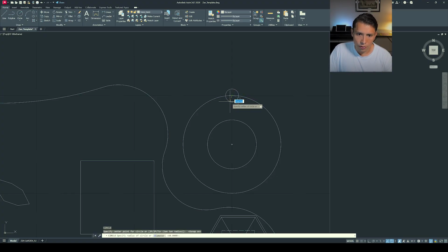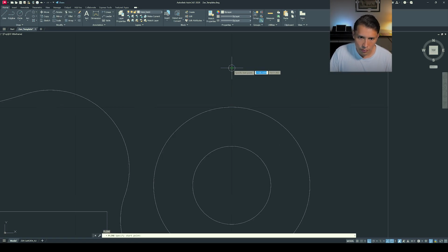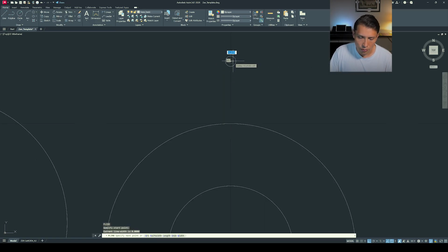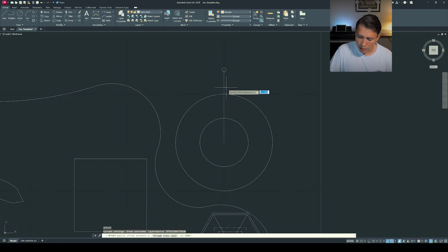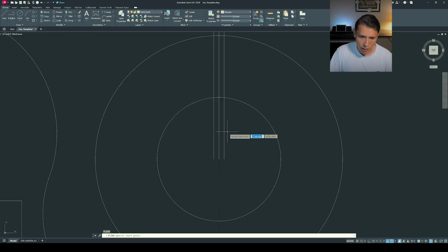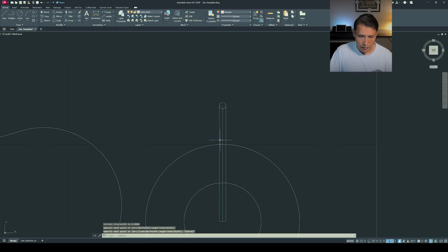I'm gonna draw a 25mm circle. Then I'm gonna move it from here up to the north 300mm. Then I am going to select another line that goes from that center up to the center. Then I am going to offset that line 25mm again from here to here and to here. And I'm gonna close right here. And I'm gonna delete the central line.